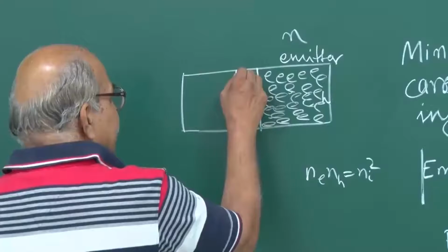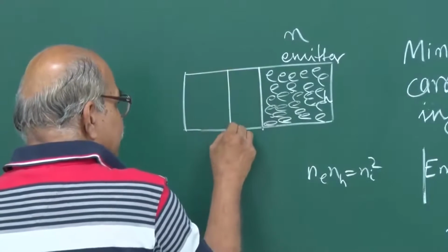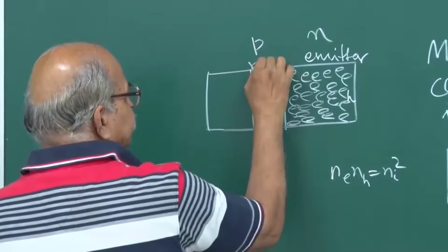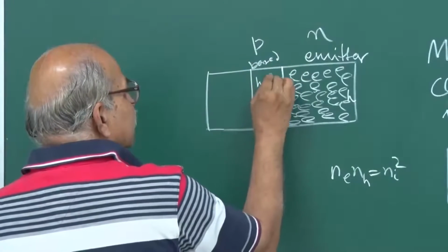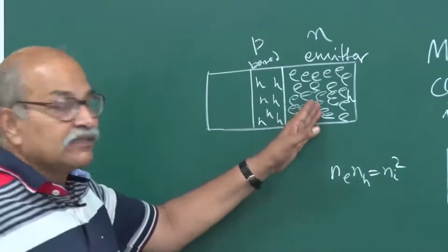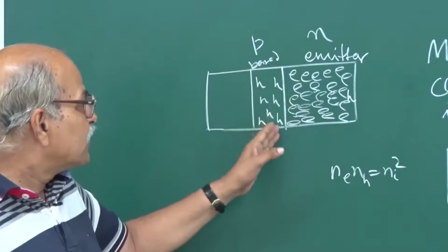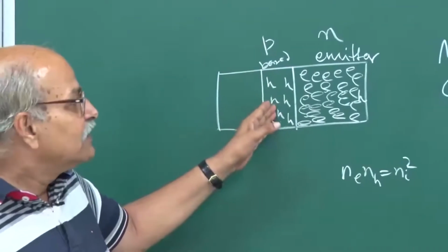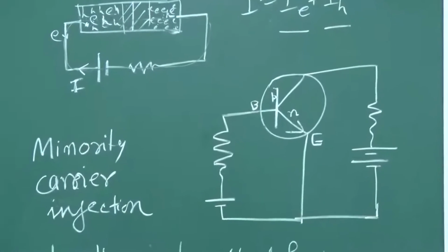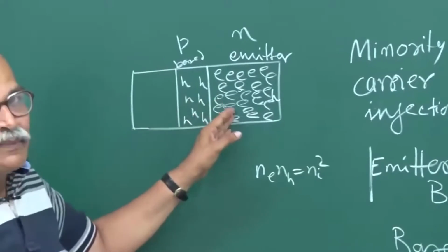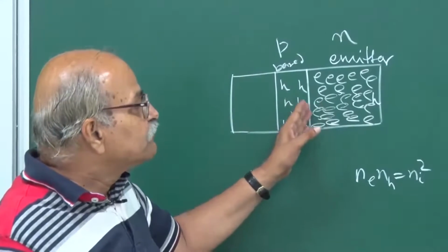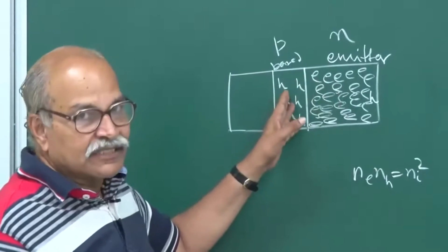And on this P side, on this base side, let me show this base here. It's not this big. So this is that base which is P type. It is lightly doped. That means even the majority carriers don't have large density as compared to this. In P type, these holes are the majority carriers, but it's lightly doped. And therefore, in this IE and IH, it will be dominated by the electrons, and this current which is there will be primarily because of this electron injection here.